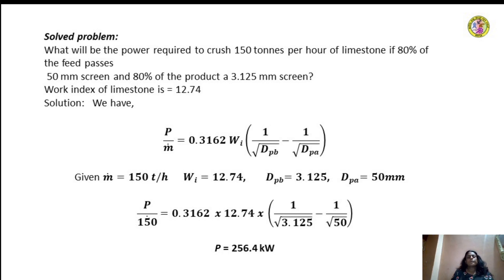Also the work index of limestone is given. Work index comes in only in Bond's law. So you are supposed to use the Bond's law statement.